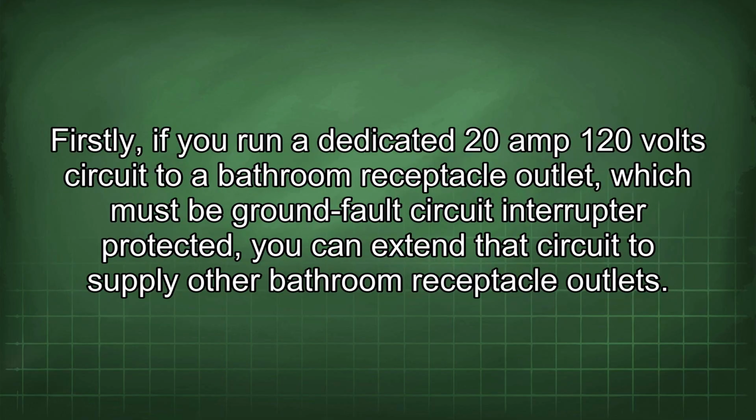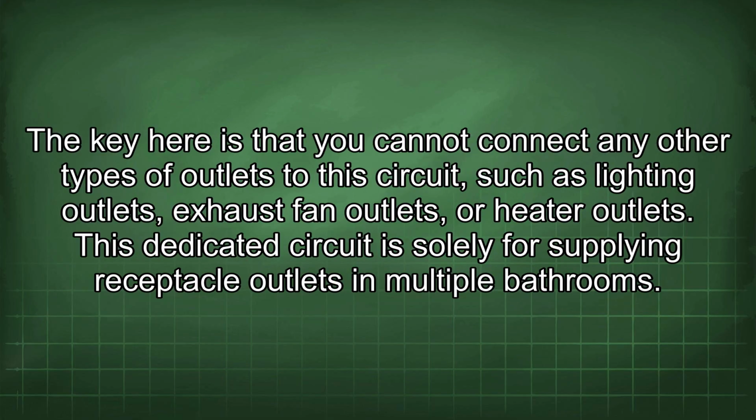Firstly, if you run a dedicated 20 amp 120 volt circuit to a bathroom receptacle outlet, which must be ground fault circuit interrupter protected, you can extend that circuit to supply other bathroom receptacle outlets. The key here is that you cannot connect any other types of outlets to this circuit, such as lighting outlets, exhaust fan outlets, or heater outlets. This dedicated circuit is solely for supplying receptacle outlets in multiple bathrooms.